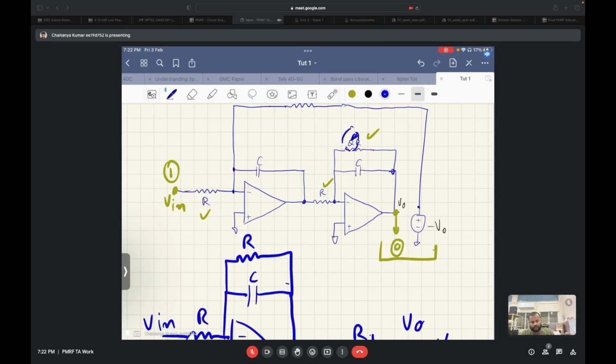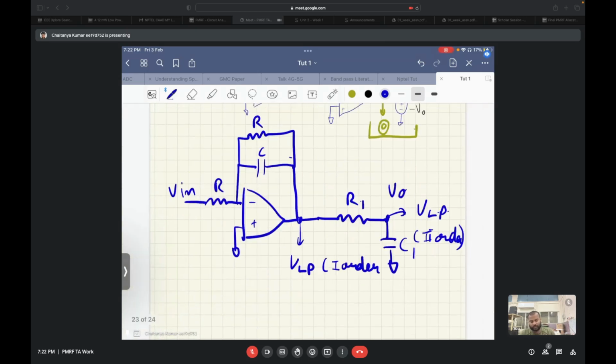We also know from control systems basics that if we introduce some positive feedback from this point to the negative terminal of the op amp, we can make the circuit slightly unstable, and we can push the poles towards the j omega axis through the imaginary path.